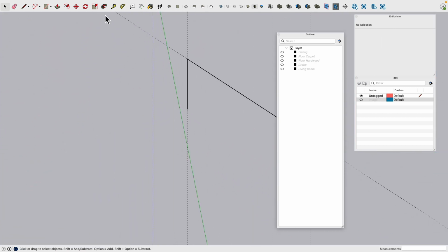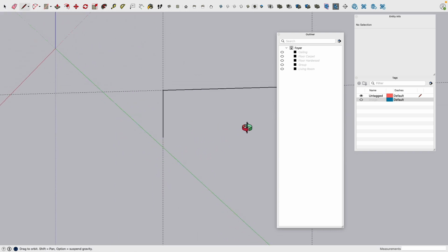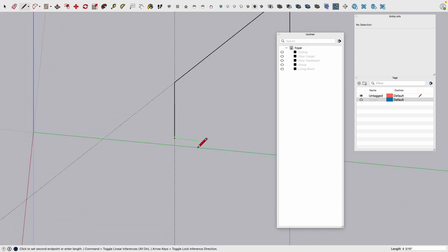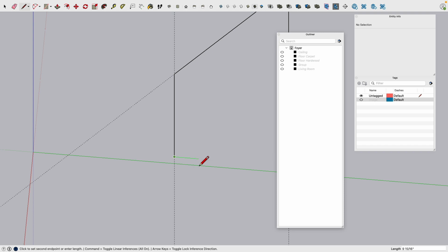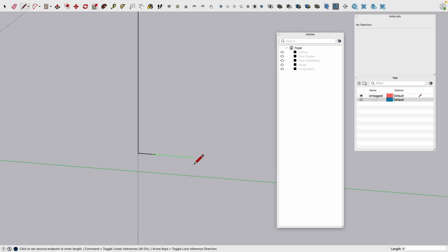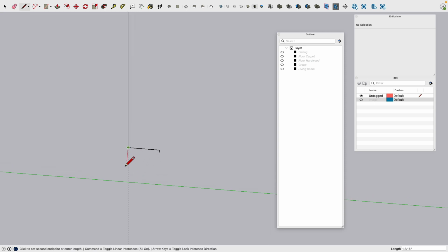Then we can maybe go to here and go to the line tool. So the easiest way is, instead of trying to draw this at an angle, I just simply follow the y-axis. Okay, good. So, 2.5 inches. No, that's what we said. Then this is the inside, 0.25. And here, that's the outside along the x-axis, 0.75.